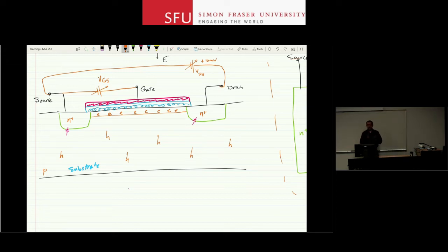So you first accumulate all the charge at the surface, all those electrons, bring them to the surface right below the gate, and then at some point you will have an inversion of the doping type. It's not a real inversion. You still have all the dopants in there, but you have so many charge carriers that it behaves as a very thin layer of an N region.